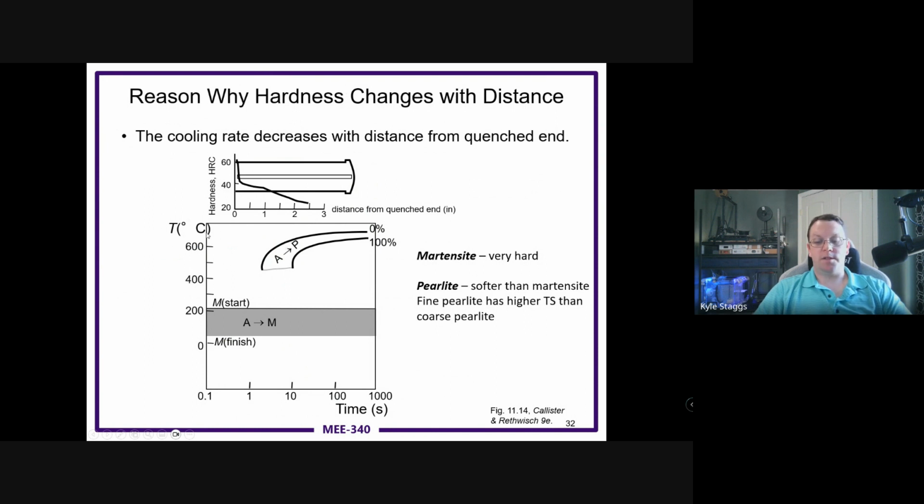So here, the path that it's going to follow, we're looking at the martensite, which is very, very hard stuff. And that's in that 210 and below region, where we're converting our austenite to martensite phase. This is kind of the path that it follows. It's opened, it cools down slowly within the furnace. And then it starts to cool a little bit as we get it quenching.